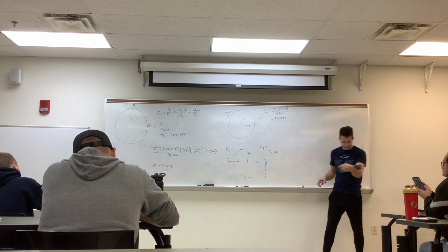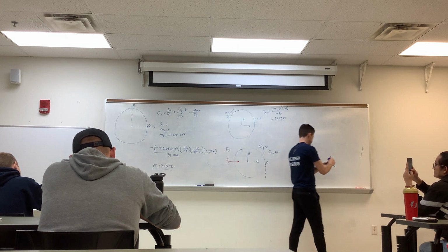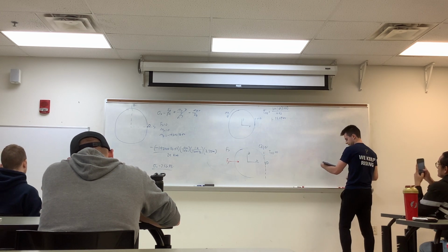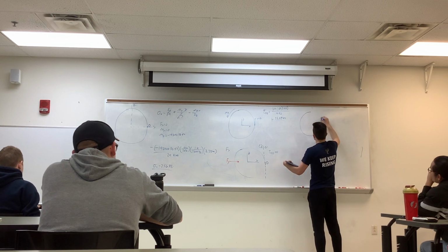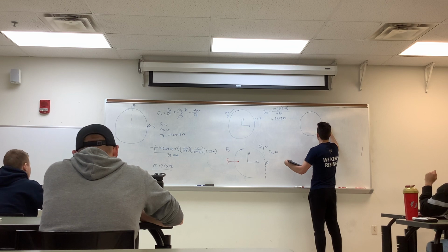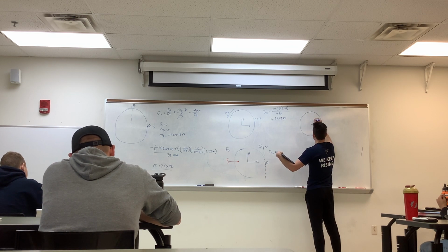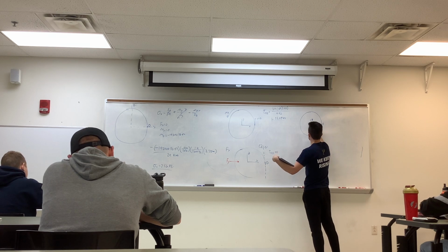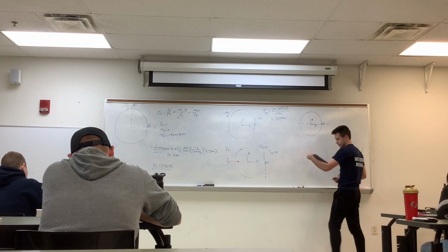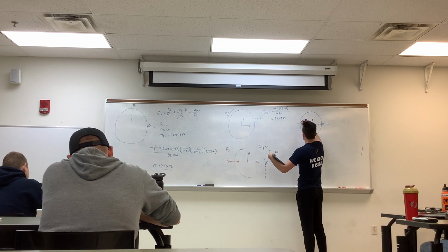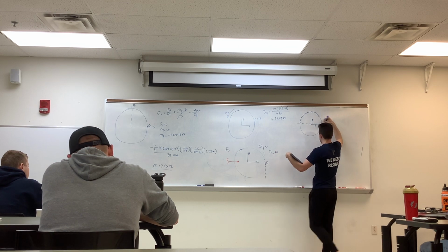And then lastly, with regard to your tangential shear being force in the z direction, we have our ring, we have point D, still have our coordinates of both y and z. Take this cut, and then we're looking at the area which is above, which is just the area of this entire ring here.